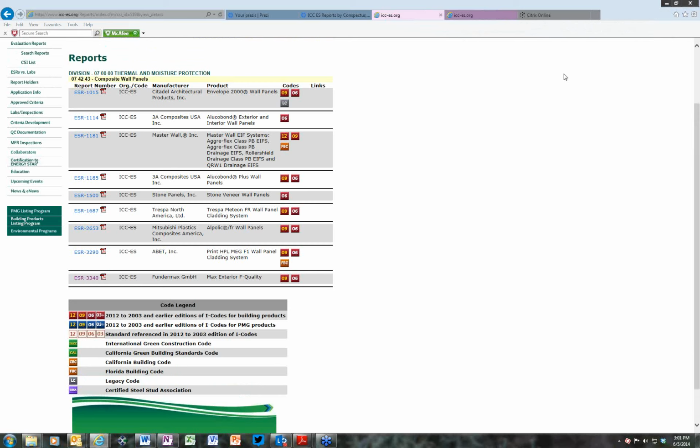technical information will be in the manufacturer's product data, but there's two things. One is they're going to organize the sequence of that information idiosyncratically, and two, the primary thing is that it's not been evaluated by an independent group such as ICC ES, and so you'd have to submit that product data to the local building official, who would then have to think about whether or not it's acceptable, whereas if you've got an evaluation report for that same manufactured product, maybe the same information, but our local building inspector knows that